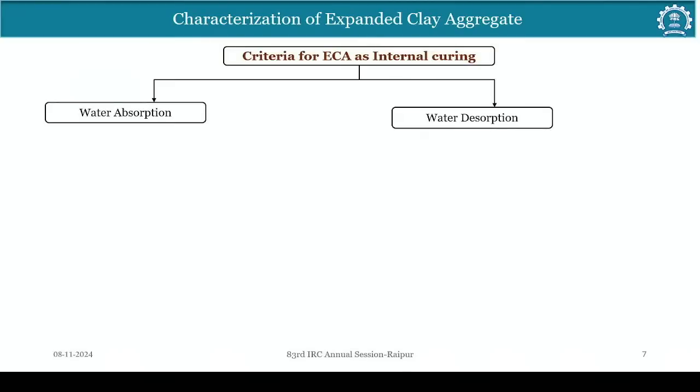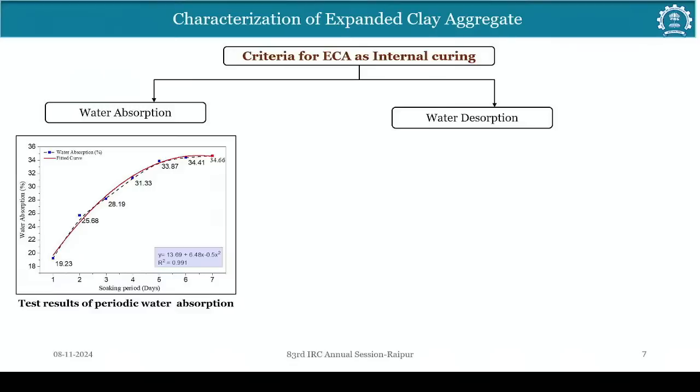In the characterization of the expanded clay aggregate, the most important aspect is how much water it can hold, and next, how much water it can release, that is, water absorption and water desorption. For the water absorption, I pre-soaked my lightweight aggregate for 1 day and then checked the water absorption. Similarly, I did this up to 7 days. I could see that up to 7 days, the water absorbed could be 34.66%. In the 1 to 4 mm aggregate size, it was able to hold 24.66% of water.